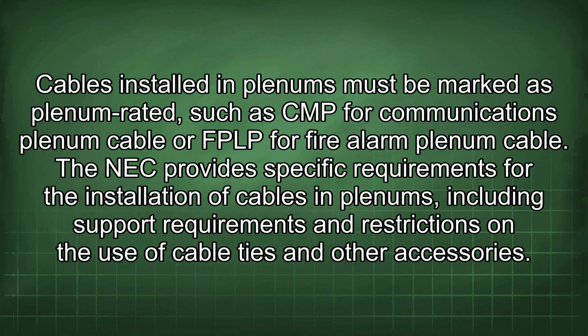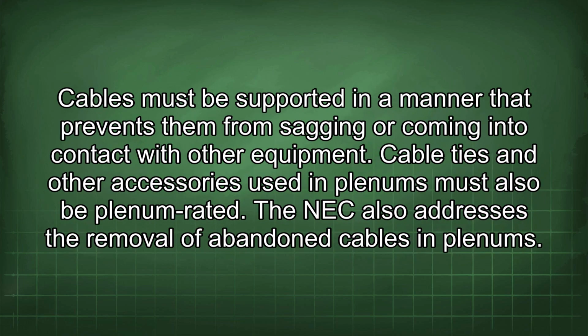Cables installed in plenums must be marked as plenum rated, such as CMP for communications plenum cable or FBLP for fire alarm plenum cable. The NEC provides specific requirements for the installation of cables in plenums, including support requirements and restrictions on the use of cable ties and other accessories. Cables must be supported in a manner that prevents them from sagging or coming into contact with other equipment.